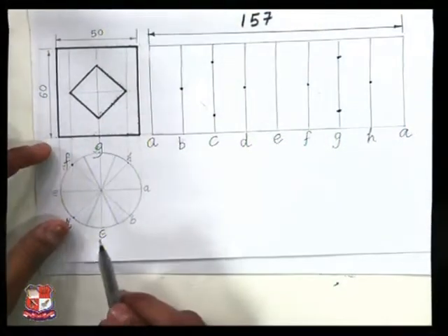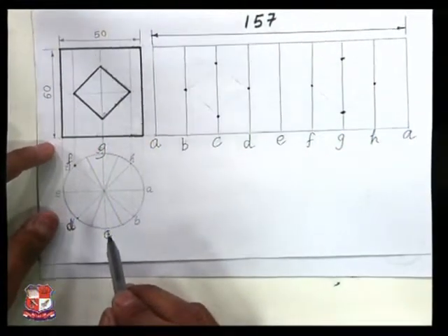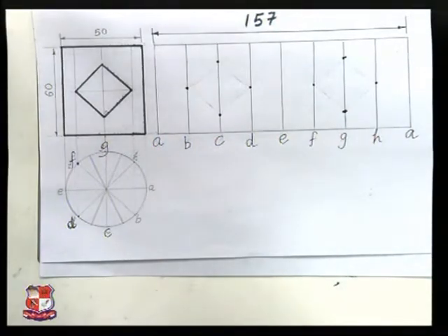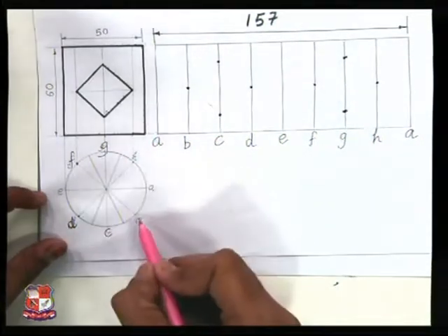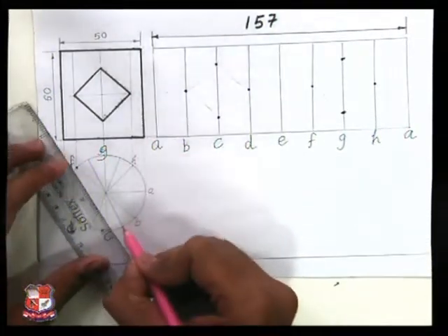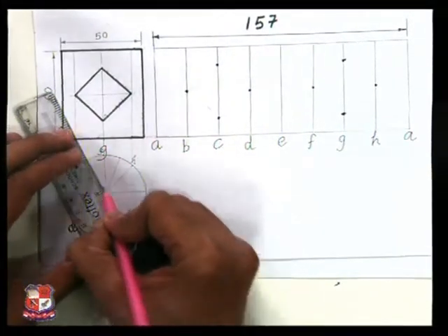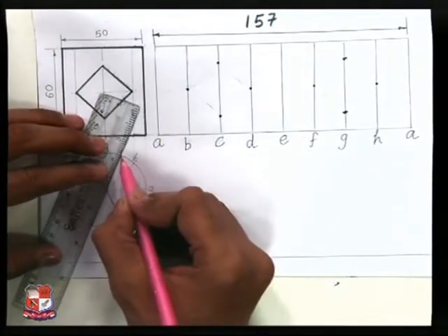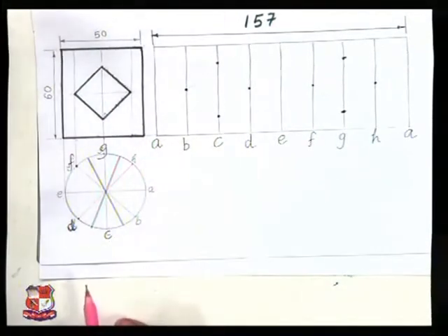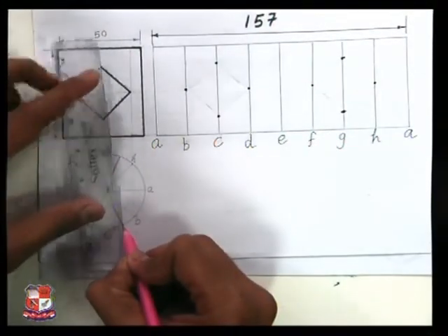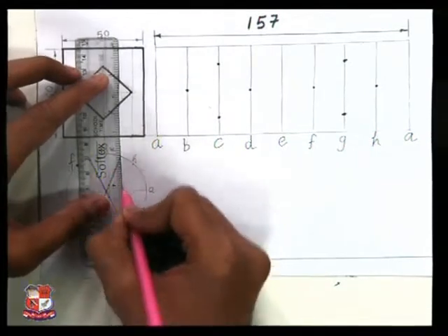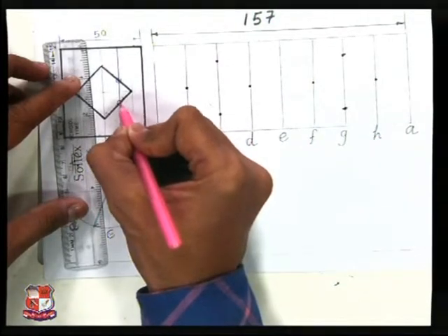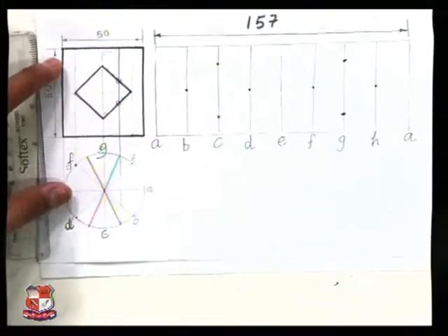What's about the intermediate point? We can locate the intermediate point by using the basic concepts like this. Let me take one exercise. So for that, divide this GH or BC into equal number of parts. So draw this line, divide BC into 2 parts. Similarly, GH into 2 parts. So we have drawn 2 more imaginary generators. From these points, draw straight vertical lines like this that will cut this square at 2 points, one over here, another over here.